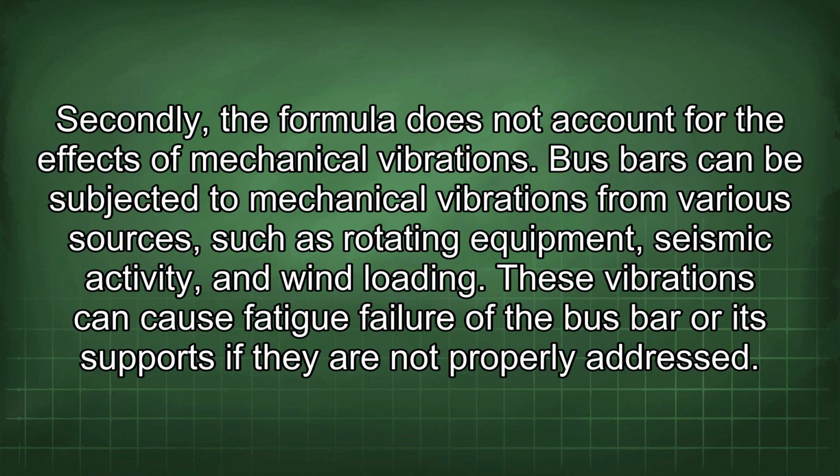Secondly, the formula does not account for the effects of mechanical vibrations. Busbars can be subjected to mechanical vibrations from various sources, such as rotating equipment, seismic activity, and wind loading. These vibrations can cause fatigue failure of the busbar or its supports if they are not properly addressed.